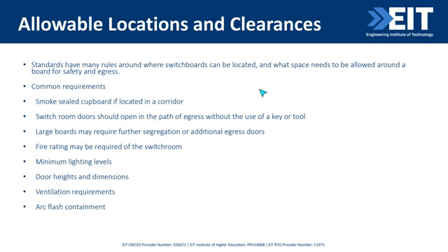Some key considerations when you are locating or designing a switchboard, or even replacing a switchboard, is to look at your relevant standards and work out where that board is going and how much space it needs. That's not only does it fit in the room, but do you have enough space for both safety and for egress, so people escaping the room.